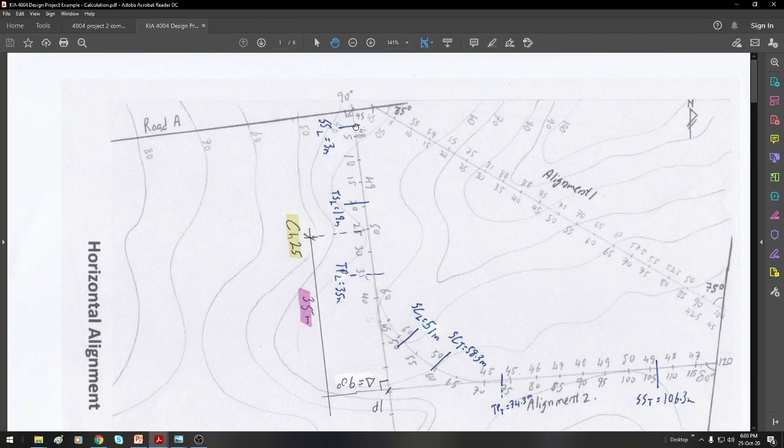But in your design project, if you're going to have a curve, you must make sure the distance between the start of your road to the point SS leading of your first curve must be 10 meters long, minimum. So this ensures when people are driving into your road, turning into your road, they will experience a straight segment first. After 10 meters, then only they experience the change in super elevation. Alright, so the first 10 meters must have normal ground.